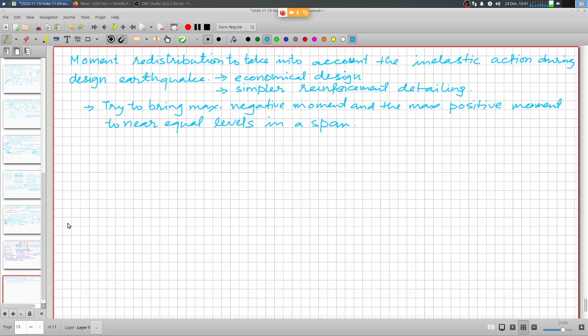Right, so if there is a very large difference between the negative moment appearing at a beam column face and the positive moment somewhere in the midspan of the beam, then we need to look at a number which appears somewhere in the middle, so that will be the target moment capacities for the negative as well as positive.